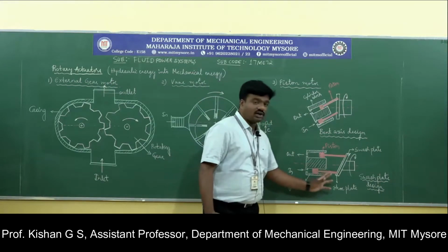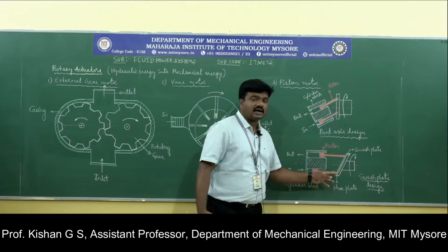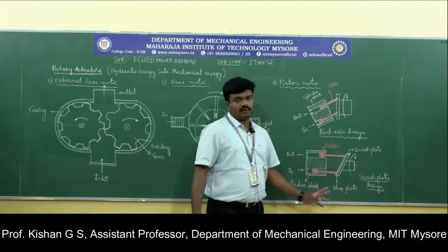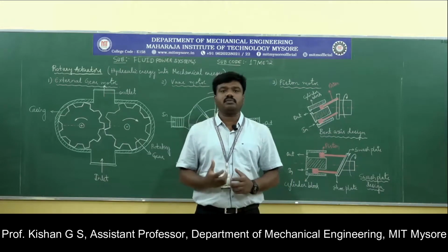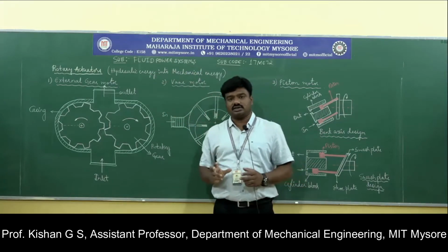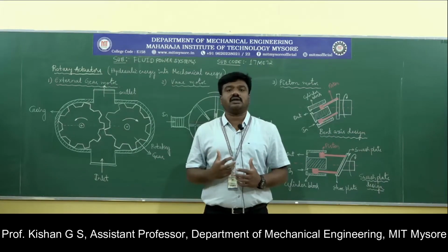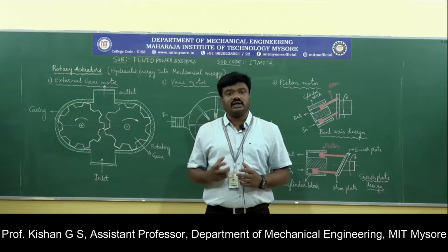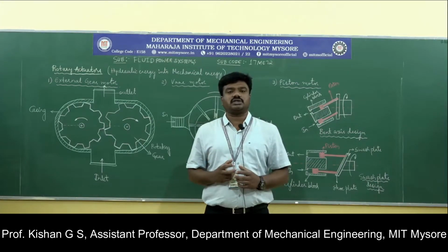Here the pistons are not directly attached to the swash plate. Instead we have one more plate which acts like a washer that houses the piston, that is nothing but the shoe plate. See, this is the construction and working of the rotary actuator. Keep in mind, the main aspect is that hydraulic energy is converted into mechanical energy. The highly pressurized fluid results in the rotation of the rotating member in the actuator that leads to the rotation of the output shaft, which in turn gives the torque as the output, or mechanical energy as the output.